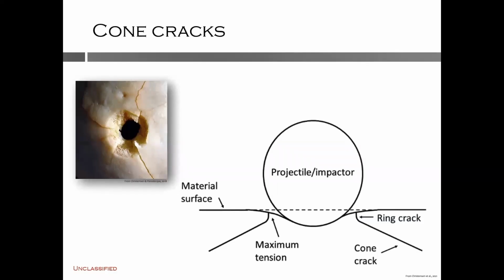When an applied load reaches a critical value, a ring crack forms due to tensile stresses on the impacted surface of the structure. This ring crack will be concentric with and just outside of the area of the two contacting bodies, which is where the tensile stresses are greatest. The initial ring crack propagates normal to the free surface of the structure for a short distance. With increasing load and shear forces, the crack will propagate outward. This outwardly propagating crack is the cone crack or bevel.